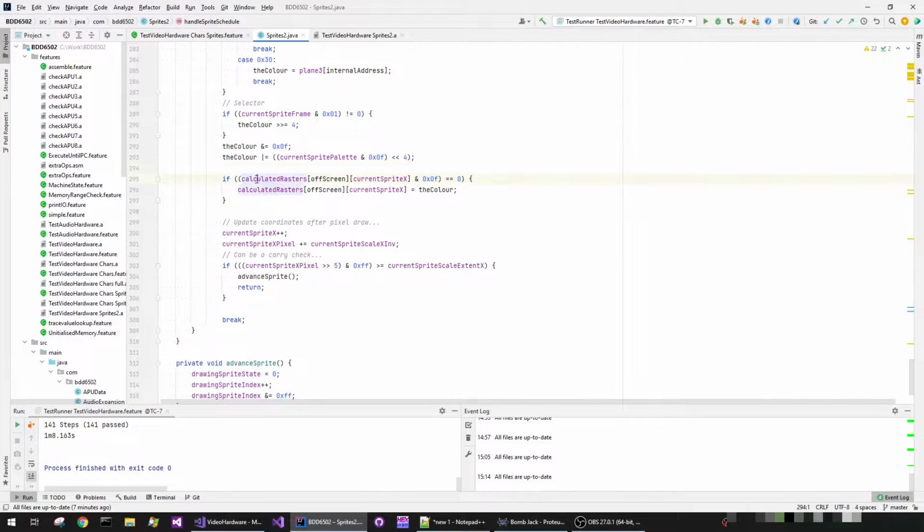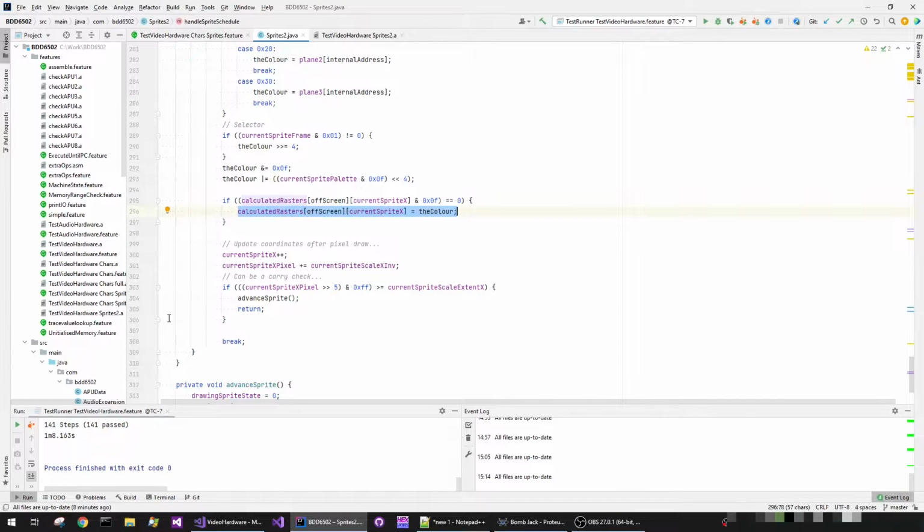And then eventually, if the sprite Scanline Ram has a cleared value in it already, in other words the pixel value is 0, then it stamps in whatever the sprite data is fetched from the sprite rams. And that's just basically a very simple piece of logic.